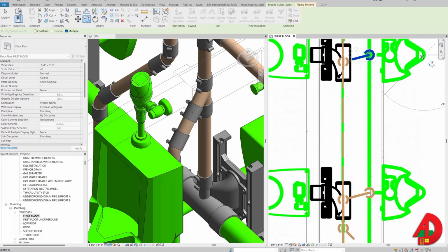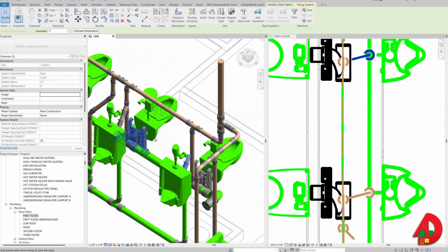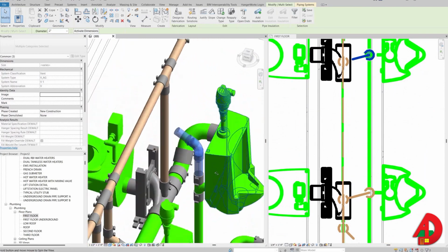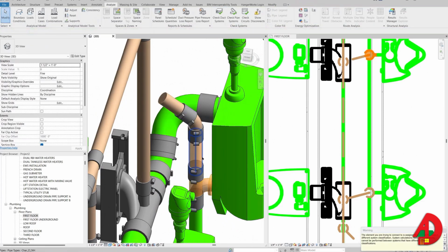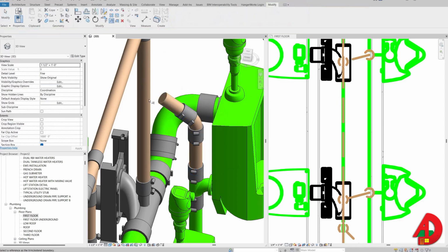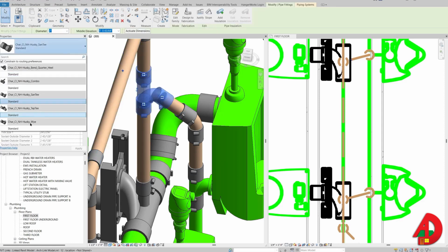the other one. Going back to my 3D view, this pipe might look like it is connected, but it is actually not. So I need to select the Tab T and connect into vertical segment. And since everything is copied and aligned, I can just extend and connect. The only thing left to do now is to turn this into a Y.